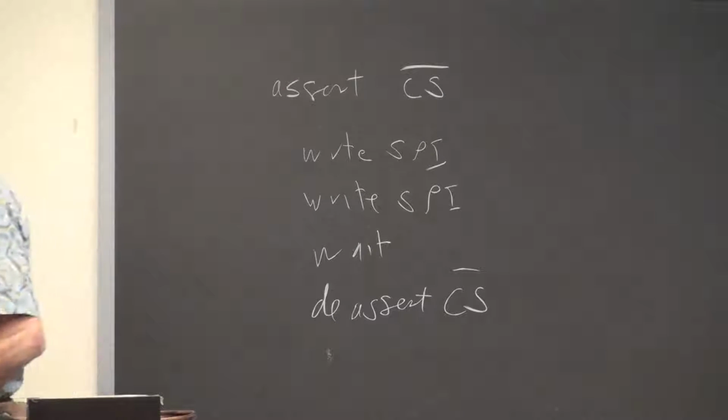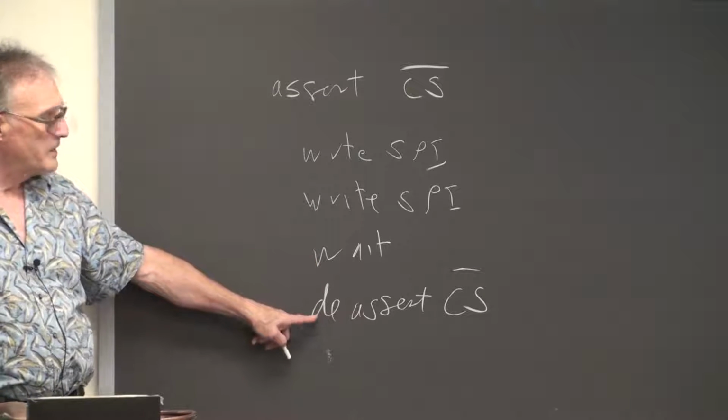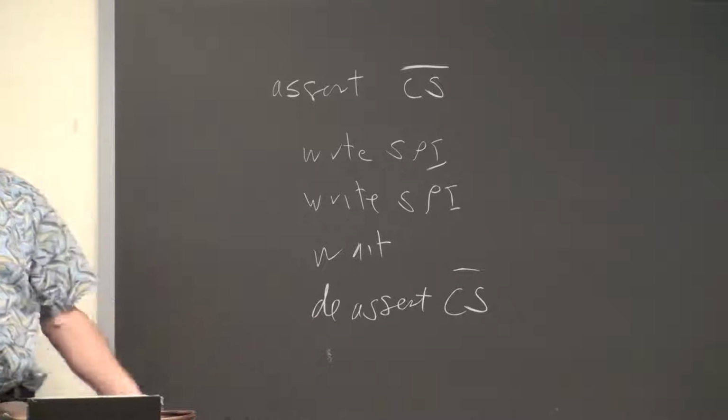What's wrong with that? So assert chip select, write SPI, wait, and deassert chip select. What's wrong with that?